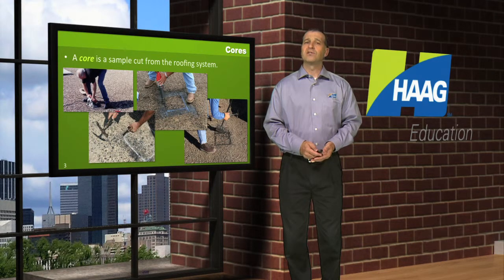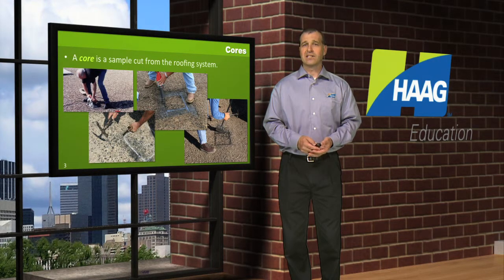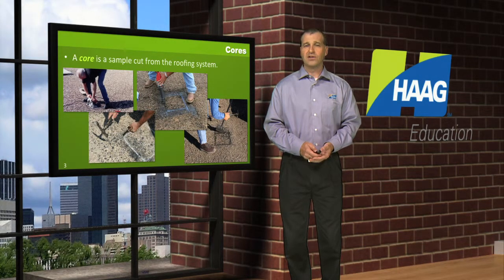If you're trying to take a test cut to determine, is there damage from hail impact, then that's got to be a slightly larger core opening, and it's got to be done at an area where you believe that hail struck with large enough force that there's at least a potential to find something in that core area. And then it normally would have to be sent off to a lab for them to de-asphalt and determine, is there impact damage to that built-up roofing felt.